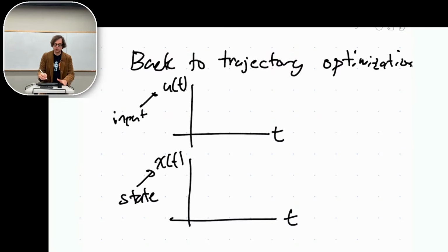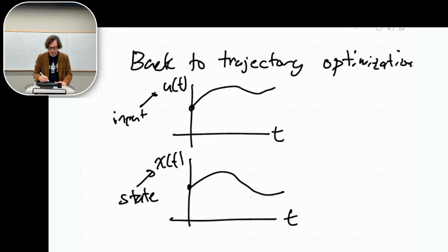And we're trying to optimize some trajectory, right? In direct collocation, we don't get this via simulation. We don't know how the state moves over time via simulation. With direct collocation, we create what we called collocation points along the way. Collocation points.